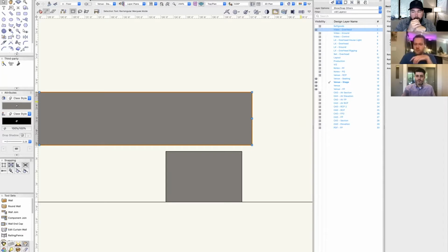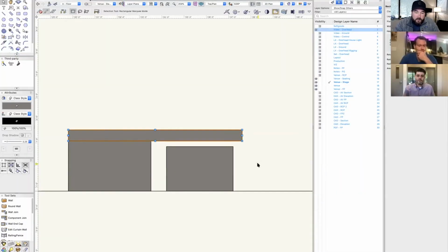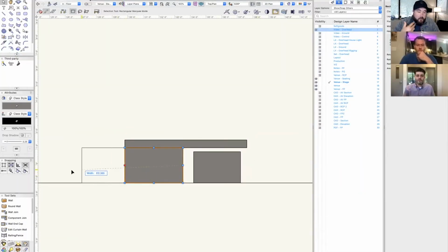There are different ways to construct a stage, but what do you typically see that stage layer being? It really depends on if we're going to be driving a lift on that stage or not. Obviously, a pan with poured concrete that's a few inches thick is preferred, because then, like you said, you can drive a lift around on those stages. That's the more expensive way to construct a stage. A lot of times, to keep costs down, they'll build it out of steel. So steel construction with usually multiple layers of some kind of plywood, and then a finished surface that gets painted, or a vinyl material or something similar goes on top.